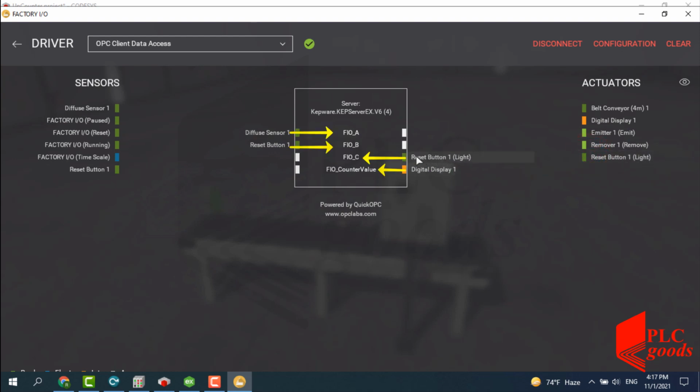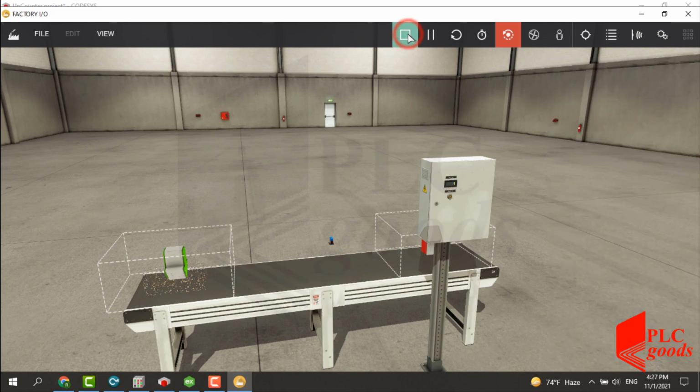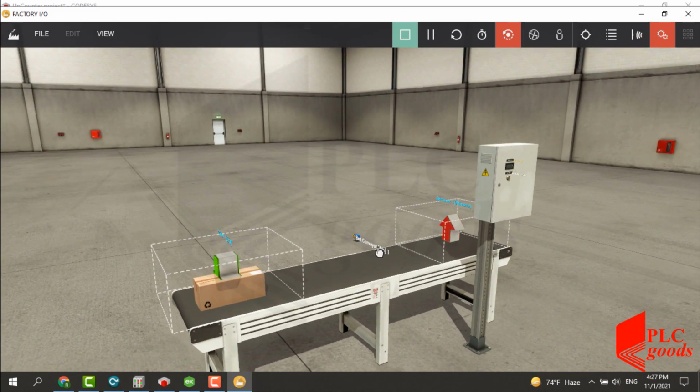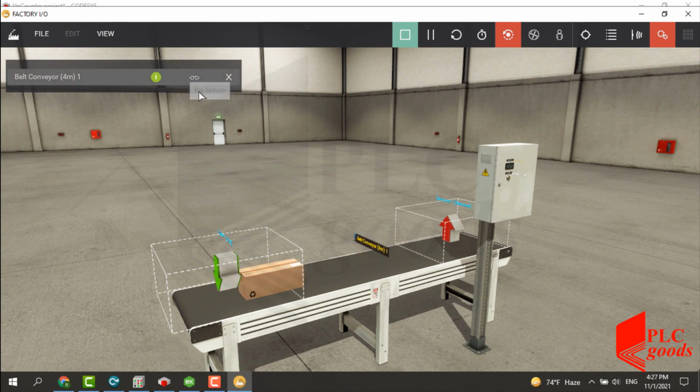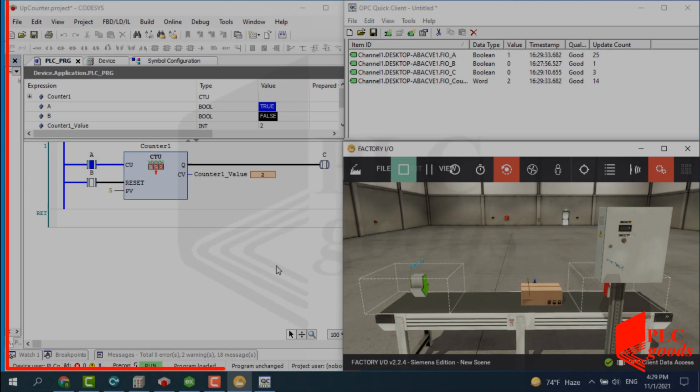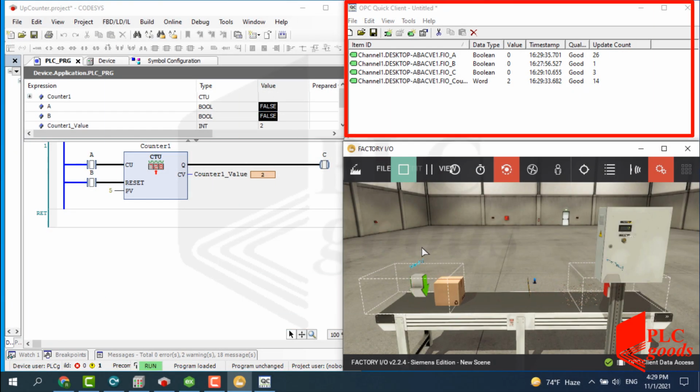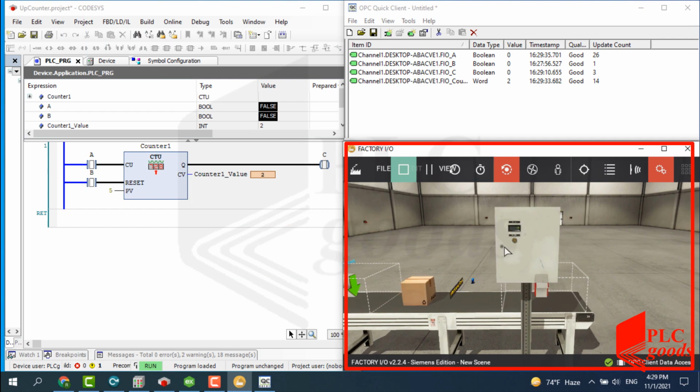Alright, the inserted equipment has been connected to these tags, which are connected to my program variables via the OPC server. Note that I've forgotten to write a program to turn on the belt conveyor. So, I run it manually by selecting its force mode. Now, let's sort windows, to have a better view of the program, the quick client window, and the design system.